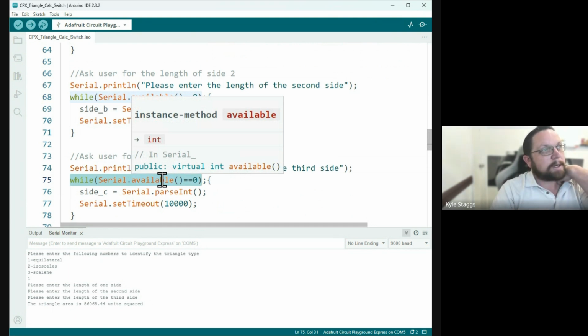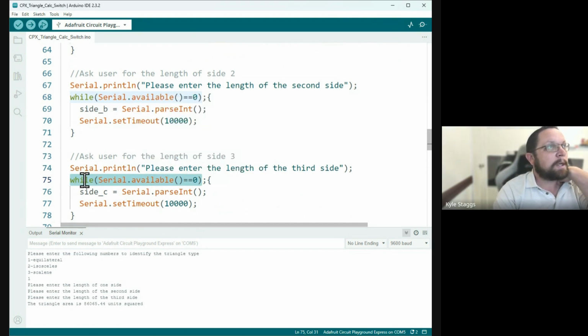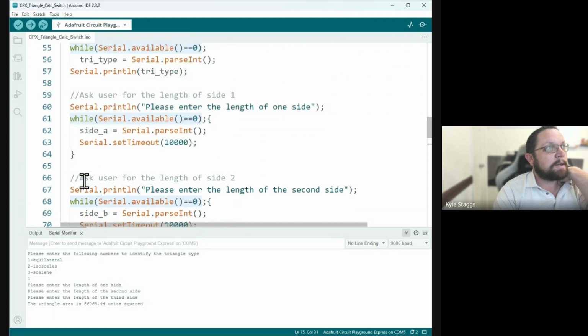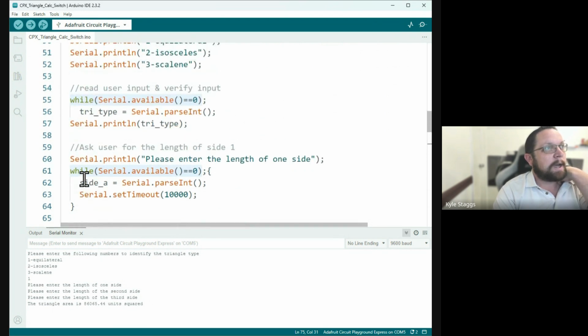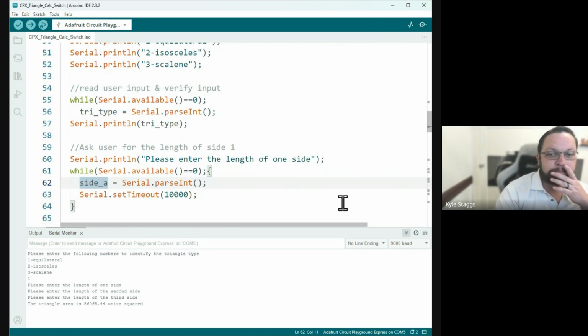So it might actually be effective instead, because of that, to add in a like 100 millisecond delay or something after this while not serial, before it tries to do a read, because it might be skipping over multiple times. That's a possibility.